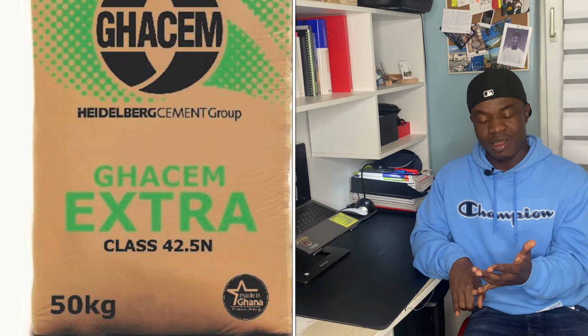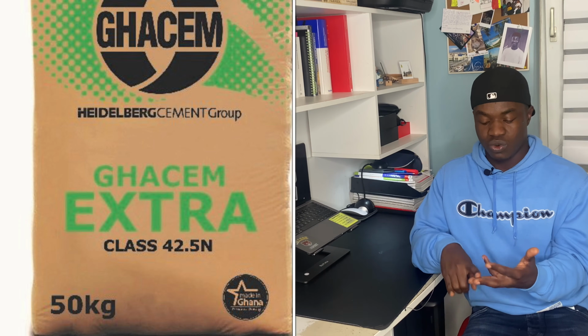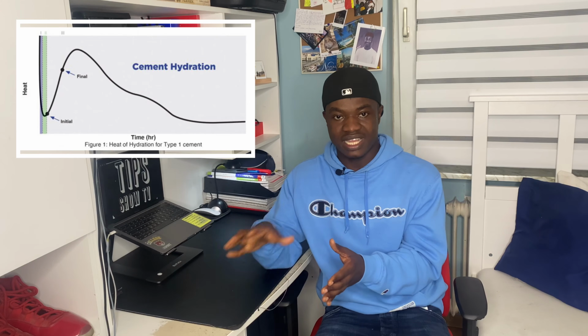Now, normally in Africa too, as I said before, we have the 32.5 and all these. We have the R, N, and L. Now the R stands for rapid, the L stands for low, and the N stands for normal. But in Africa, normally we use the R because of our weather conditions, so that it can hydrate fast, as in the heat of hydration can occur fast, as in the water cement ratio balancing reaction can balance fast. Let me put it that way, it can react fast so that we can get the initial strength very fast. So the rapid is normally used in construction in Africa.